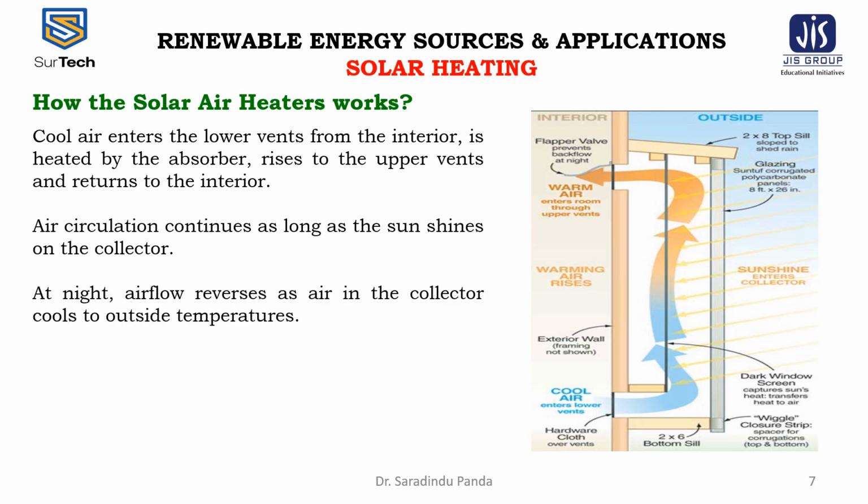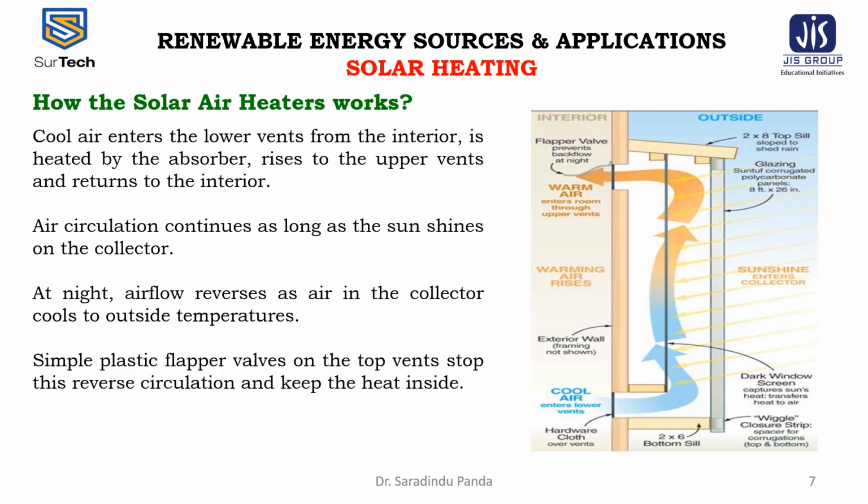At night, the airflow reverses as air in the collector cools to the outside temperatures. Simple plastic flapper valves on the top vents stop this reverse circulation and keep the heat inside, which are shown in the figure as the upper portion. The flapper valve is there.